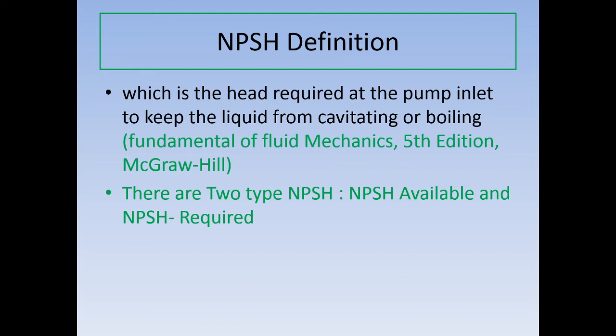But if you never test the pump, it's quite difficult. So I would like to repeat again. You have the pumps and you want to test, let's say, from 73.35 meter cubic per hour. So you want to know the NPSH required at that specific flow capacity.